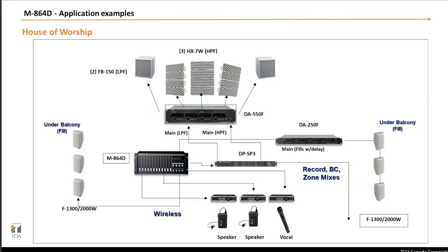So basically, we have 3 wireless microphones connected to the M864. This is going to the DPS SP3 for speaker processing and delays. And we have an output going to the DA550F. The diagram is not totally right. The second line should go to the DA250F in order to boost the under balcony speaker that is in this project.